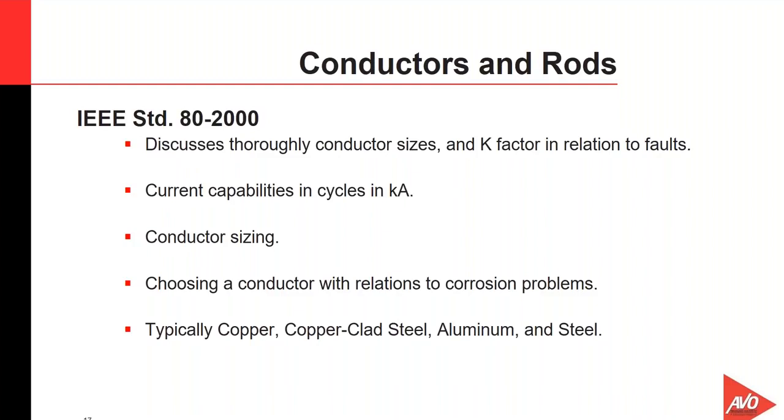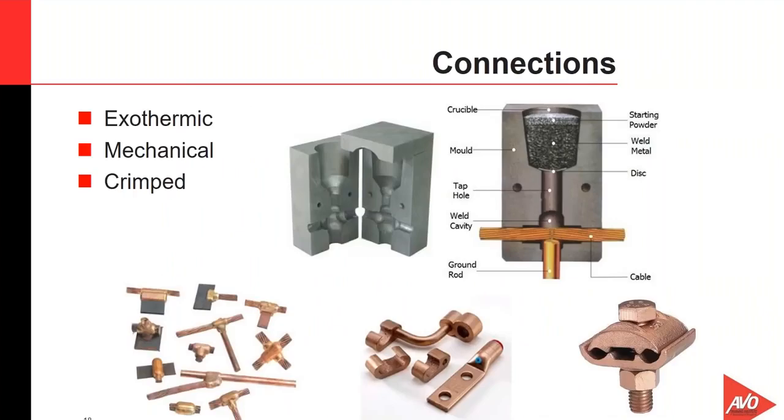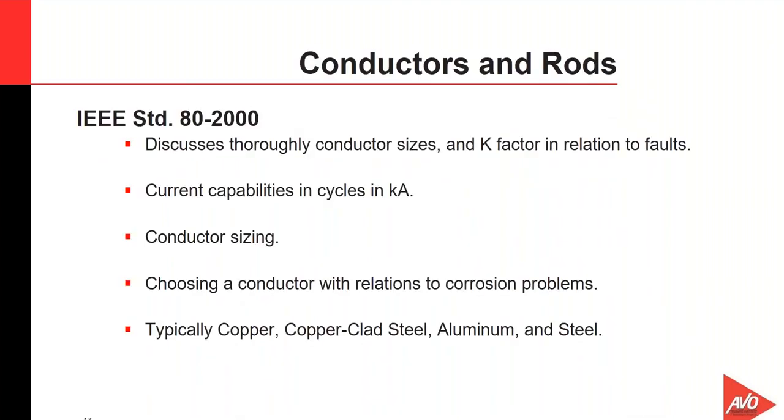So what IEEE says in IEEE Standard 80-2000, just to give you a little bit of information about that, it says directly that each part of the grounding system, including the ground conductors, all connections, connecting leads, and all electrodes should be so designed that for the expected design life of the installation, the elements will have sufficient conductivity so that they will not contribute substantially to local voltage differences, and resist fusing and mechanical deterioration under the most adverse combination of fault magnitude and duration.